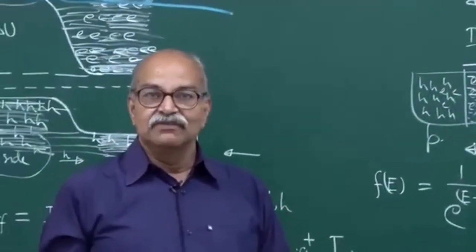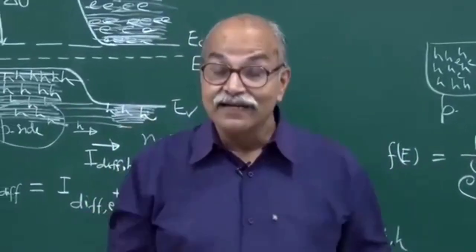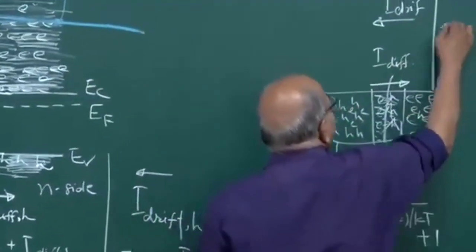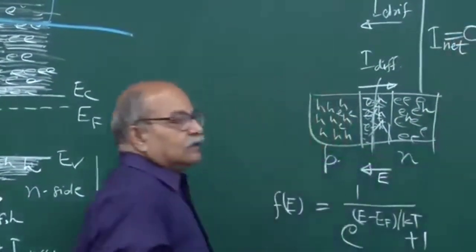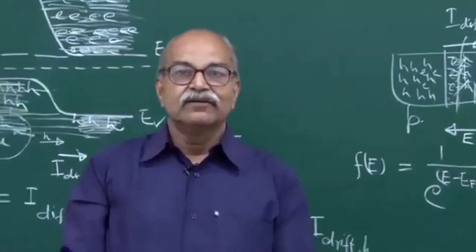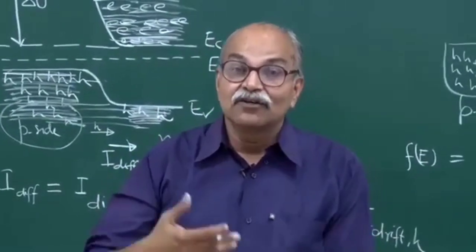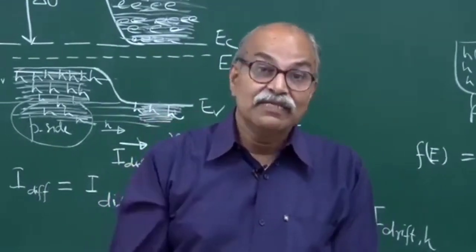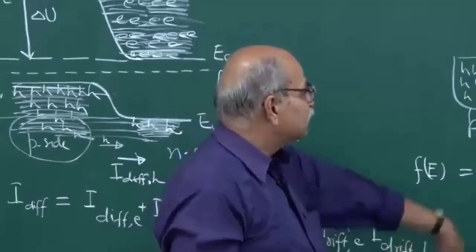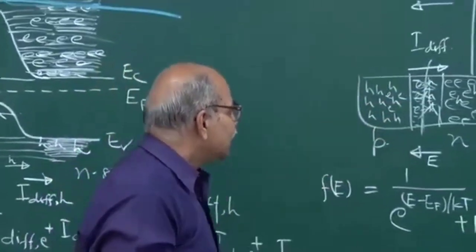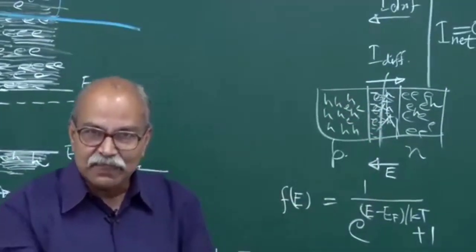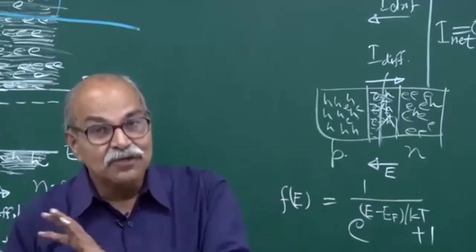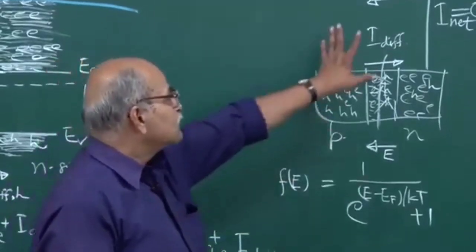And in equilibrium, when you have not added any external circuit, there is no net current, and so these two are equal in magnitude, giving you net current 0. So that is when your PN junction is just lying on the table, the activities are on: thermal generation of minority carriers is taking place, electron-hole pairs are being generated, and recombination is also taking place. There are some nice mechanisms which are different for different kinds of semiconductors, so I will not go into that, but it is happening. Because of majority carriers, you have some kind of migration of charges, then you have minority carriers, which are also contributing another kind of current, but the net total current is 0.